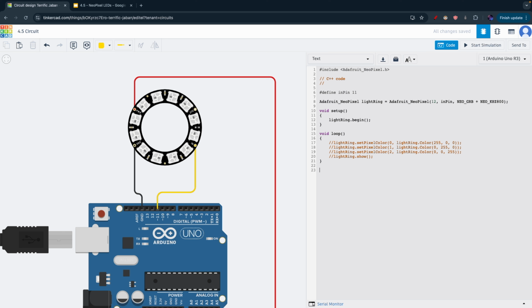So the way you write a function, right? First of all, the way you have to think about it is, what is a function doing? That's the first thing you have to think about. In this case, the only thing that the function is doing is turning on the LED strip, which means that when I call this function inside loop, I'm not expecting to get anything back, right? This function isn't returning anything to me. It's just doing something for me, right? So in that case, when you're not expected to get anything like a number back from your function, you type void, okay? And then you give the name of your function.